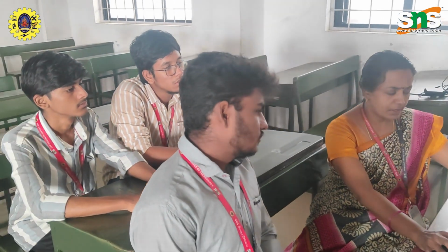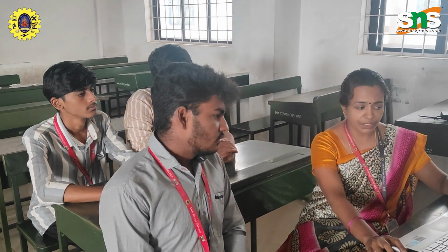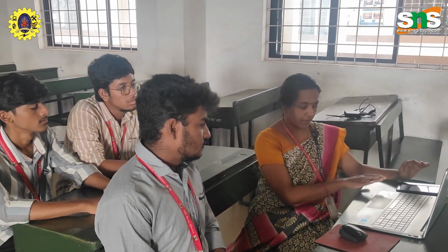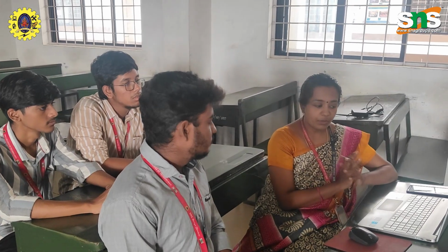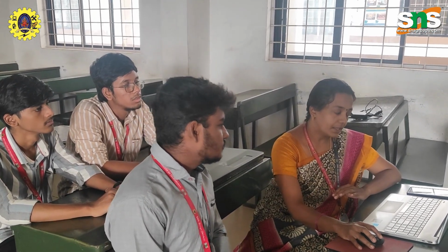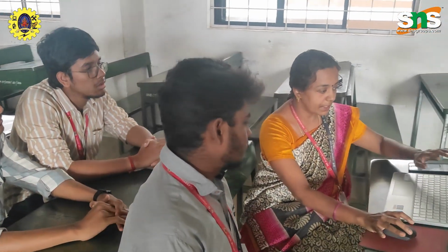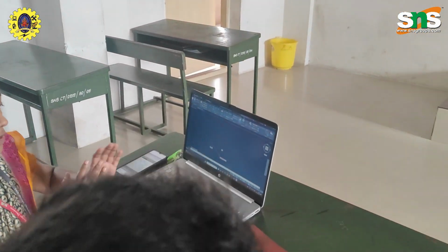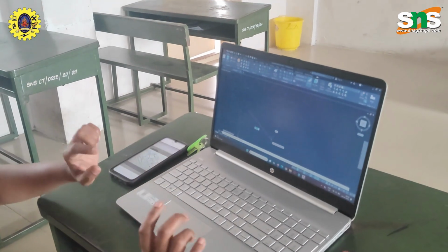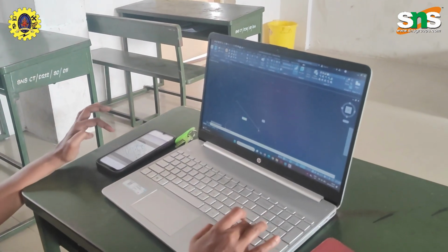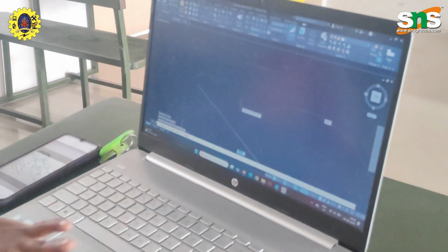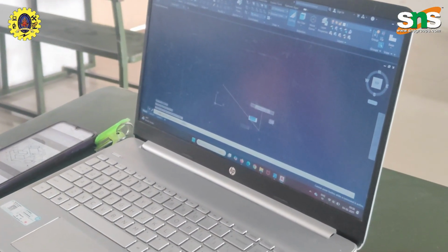The line is getting into an angle of 40, 50, it is not straight. So I press escape and turn ortho mode on. This is also very important while drawing an isometric diagram. Now again I select the line. See here, I am getting a perfect line of 30 degrees alone and the line is not fluctuating. I want a straight line. My dimension is 40, and I have drawn the 40 dimension line. Now I cannot see the line, so I zoom in, and then zoom out.